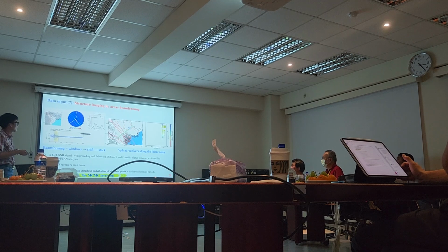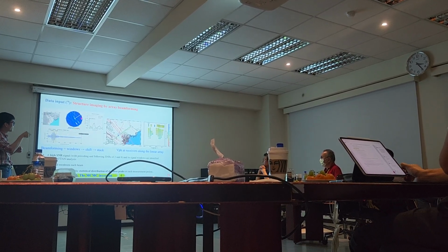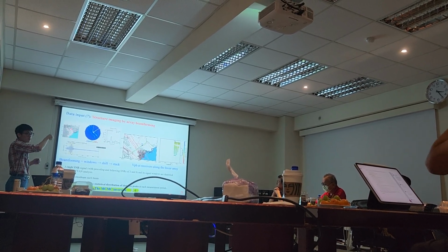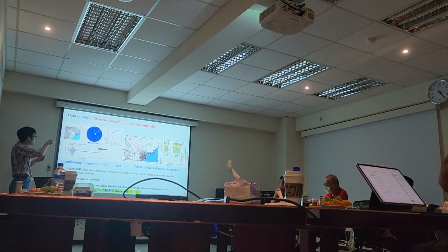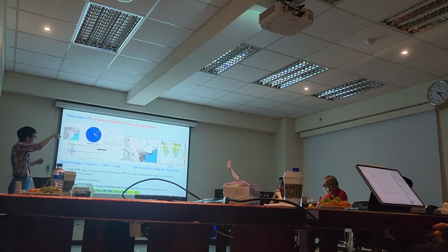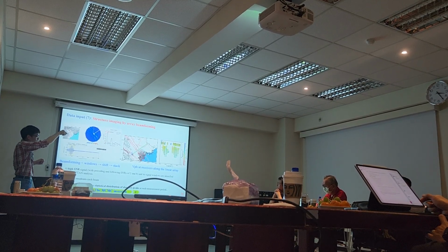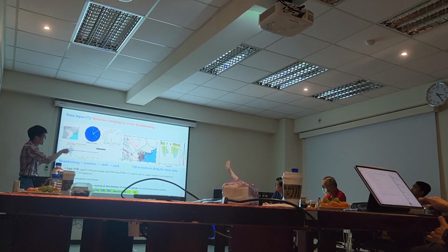Here is an example I processed for a linear array. You can see the diagram here. Because we already know the virtual source and the station, we know the azimuth and back azimuth, so we simply search along this back azimuth and find the highest peak. This extracts the peak slowness here, and after that we can translate it into velocity.